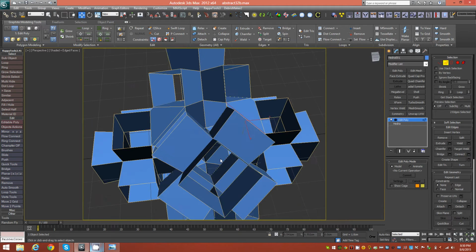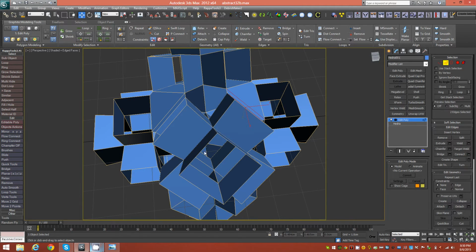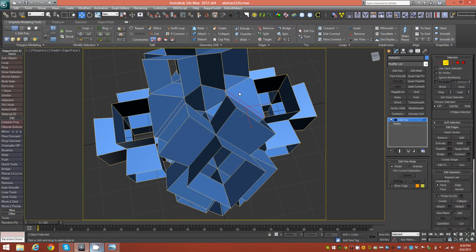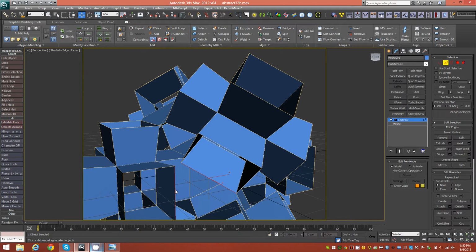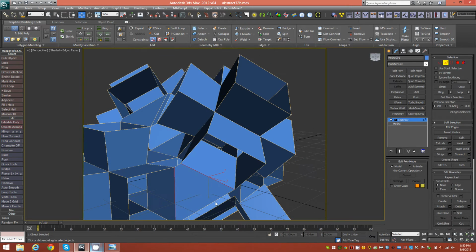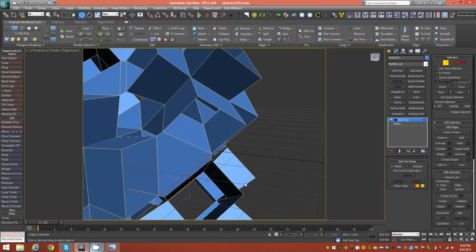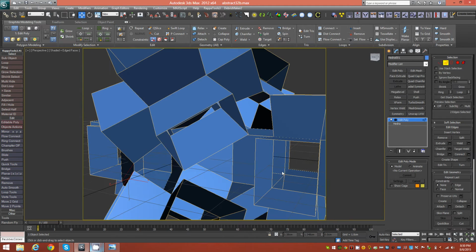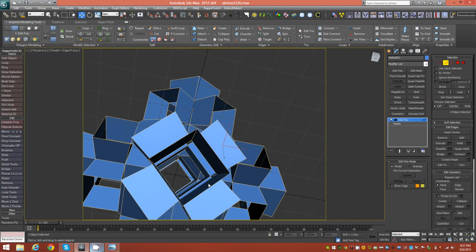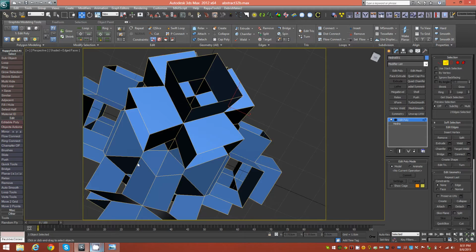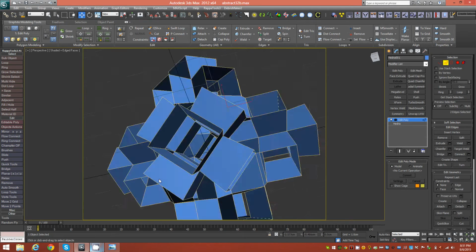Now we're tumbling around again, and you can see on this other X, the top two arms are in fact attached, so we're going to do the bottom portion. I'll bridge those, and select these two edges and bridge. And we'll roll over to the other side here and repeat. This is just a repetitious procedure, but very necessary to get the result we're looking for. Then we go underneath, and at this point you'll see that we've completed all the way around.